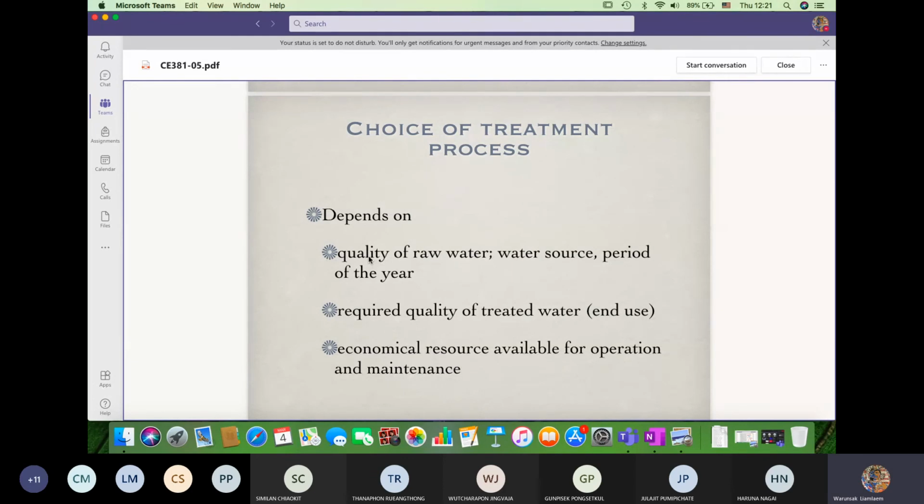In some countries, they have very stringent effluent quality. In Thailand, the COD, chemical oxygen demand, we require to be less than 120 milligrams per liter. That is good enough. So as long as the wastewater contains COD less than 120 milligrams per liter, that one is good enough. But in some countries, like in Vietnam, I'm not sure, in some particular areas, they have made the effluent standards much more stringent. They make it like only 60. So 120 is not enough. The effluent must go below 60.